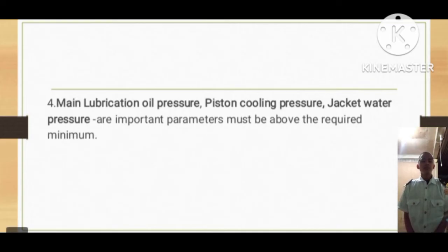Piston cooling pressure is monitored by a pressure switch. The output signal from the pressure switch to the engine control unit can only have two distinct positions, on and off. The switch is supplied with current from the engine control unit. A preset pressure limit determines when it switches on. The switch opens if the pressure exceeds this value. The idle switch can be closed with the fault code being formed. Then jacket cooling: the enclosed space surrounding the cylinder block of an internal combustion engine and containing the cooling liquid.